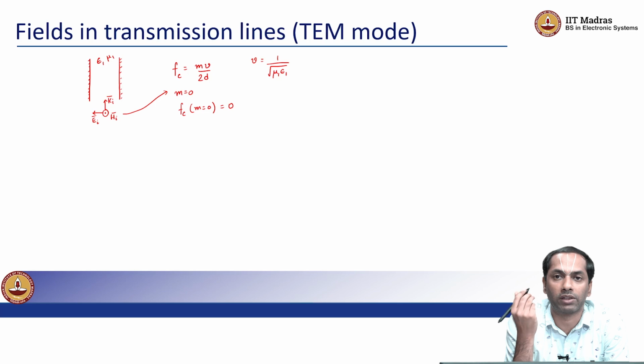One would have to make special cables for higher frequency operations, but even those, if you notice that there are two independent conductors, a signal conductor taking the signal from the source and a ground or return conductor bringing current back from the load, then the mode that is operating in such transmission line systems is the TEM mode.